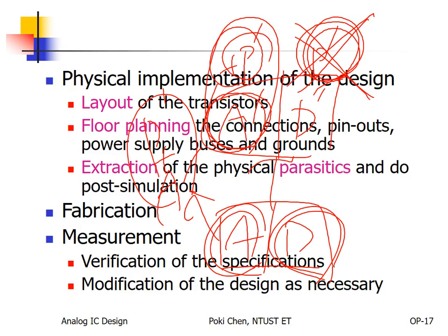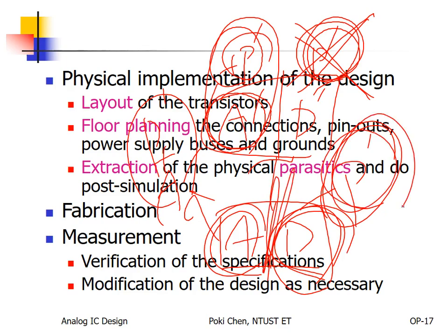After you get a good enough result, then for the final run, you include the parasitics of your digital circuit. That's it, to make sure your digital circuit can drive your analog one, and your analog circuit can drive your digital one. With the parasitics of the digital part, you want to make sure the interface between analog and digital is correct. Please keep this in mind. Then your design will be much faster than the others.